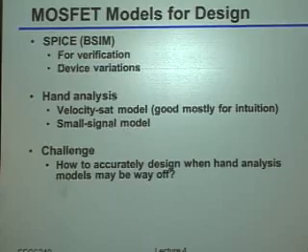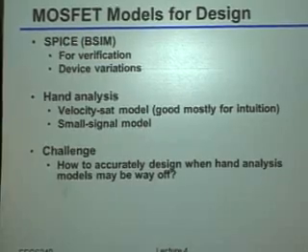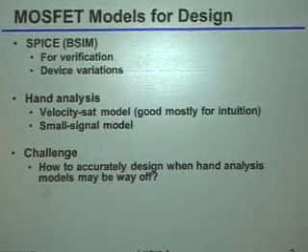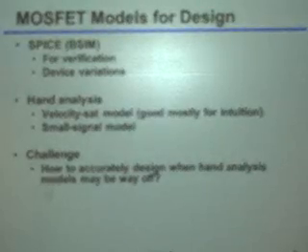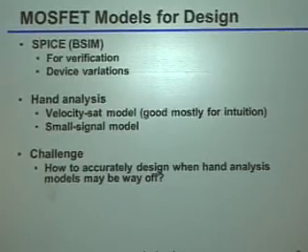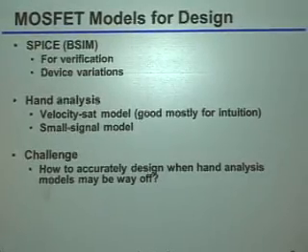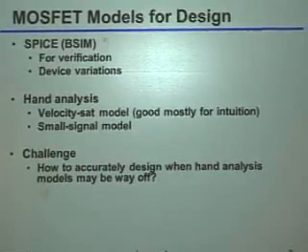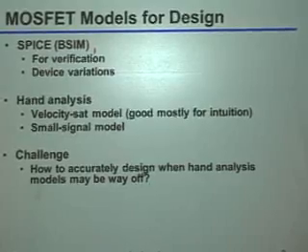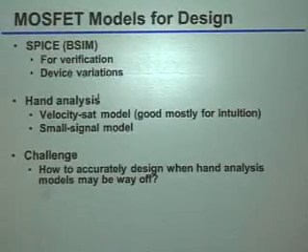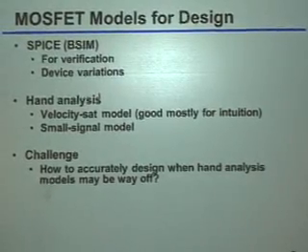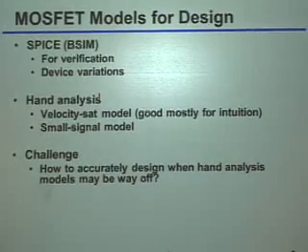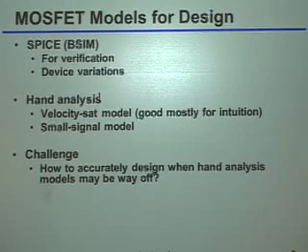So just for the video to pick up, we're now talking about lecture notes number 4, which is essentially about small signal design, or really how we're going to do small signal design, but hopefully in a much more productive way than just brute force sweeping things in HSpice. As we said, Spice is really good for verification, but we would like some kind of hand model to allow us to come up with a reasonable design procedure. But of course, the problem is that all the hand models we talked about were way off for any kind of modern transistor.